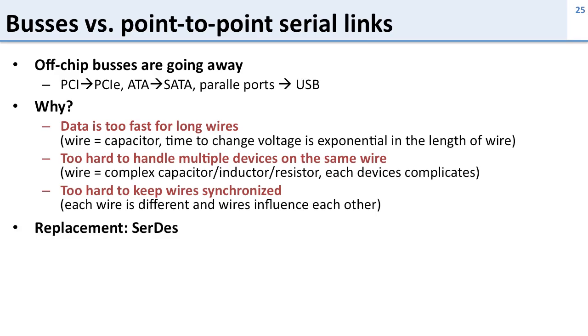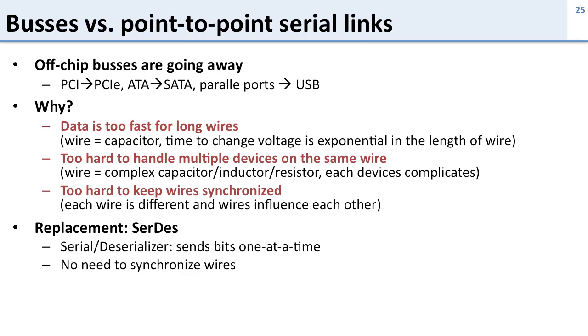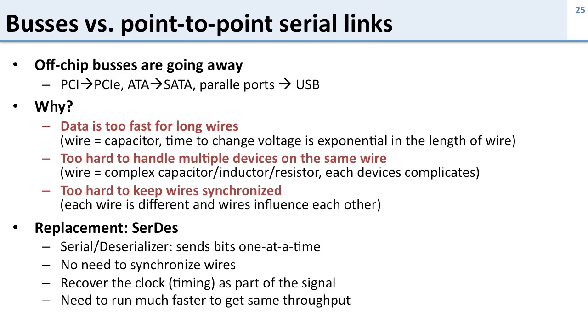So the replacement, as we talked about, is serial communication, or SERDES. This stands for serializer/deserializer, and the idea here is we send 1 bit at a time. So there's no need to synchronize the wires because we're only sending 1 bit at a time. We figure out the clock as part of the signal. This is well known how to do, although it is tricky. But we do need to run much faster to get the same throughput.